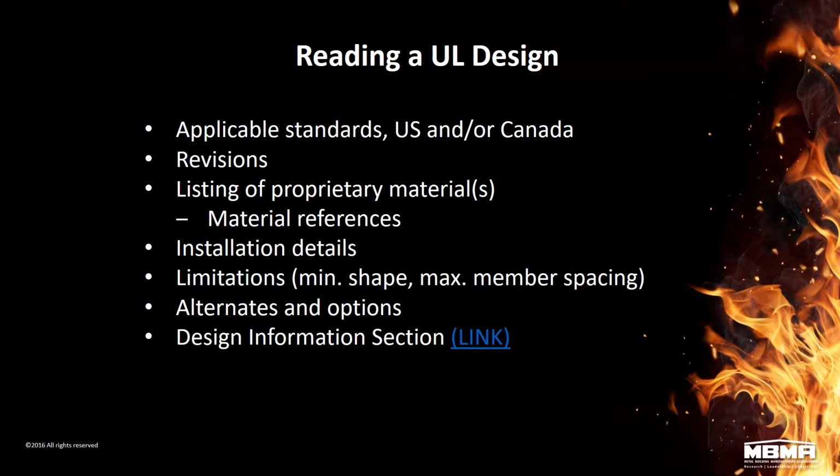Now, in terms of applying and understanding a UL design, these are governed by ASTM E119 or the equivalent UL 263. For Canada, there are equivalent Canadian standards that are basically quite similar. The rated assemblies are all rated to these standards.